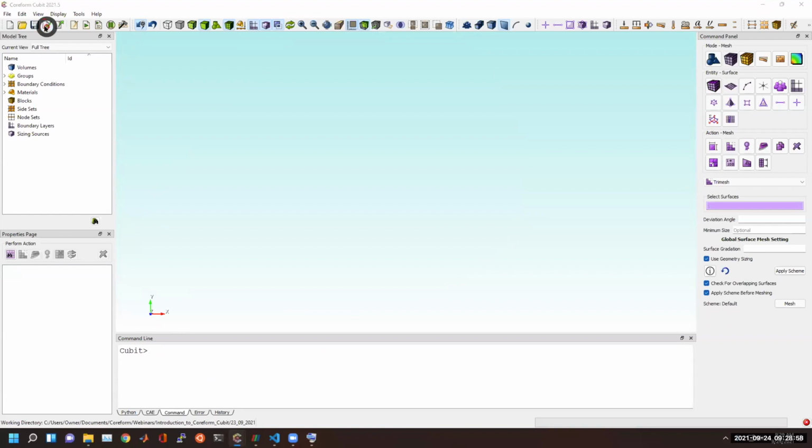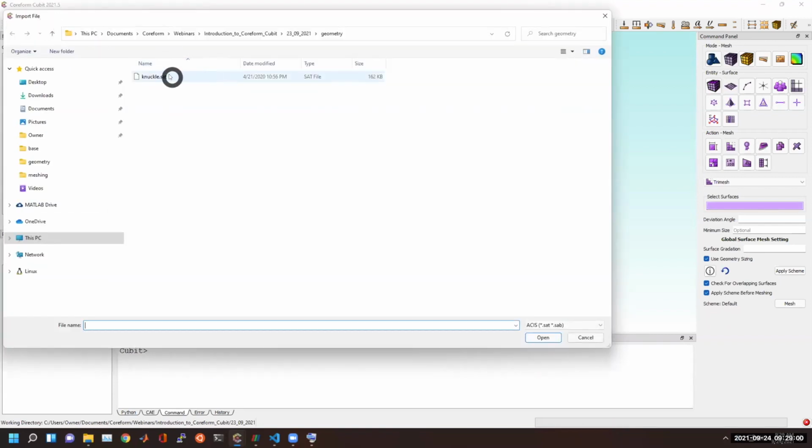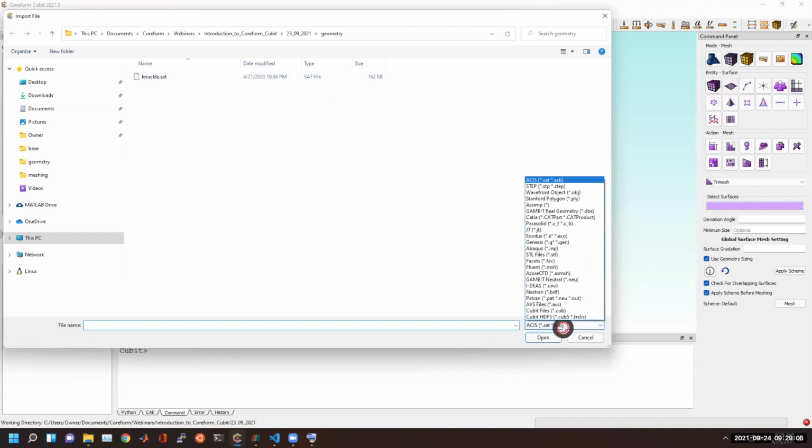If we didn't want it to respect the features, well, I guess one thing is you'll want to have at least one curve, because the meshing algorithms that we license and that we use in Cubit all require at least one curve to start the meshing. So it meshes a curve and then it meshes the surface around it. So it is useful to have at least one curve in your model. But there are cases where you may not have any curves.